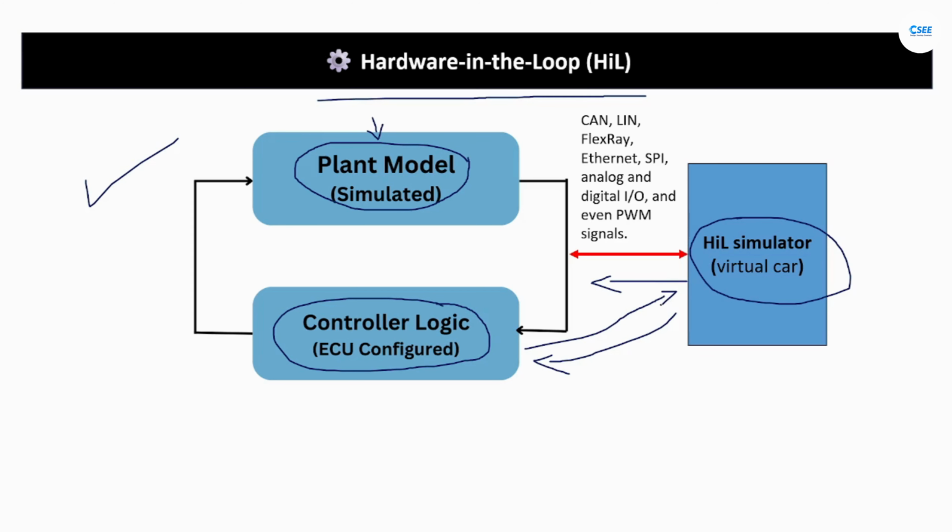To make this happen, the simulator is connected to the ECU using real interfaces: CAN, LIN, FlexRay, Ethernet, SPI, analog and digital inputs and outputs, and even PWM signals. The timing is real, the signals are real, but the vehicle is simulated. So you are testing the ECU as if it were installed in a car, only you are sitting safely in a lab.